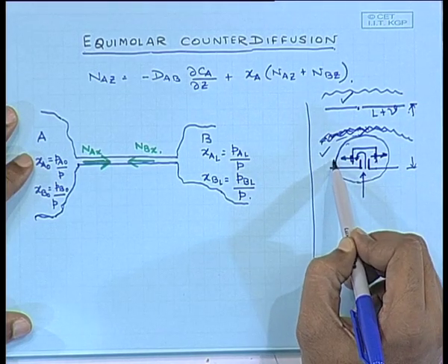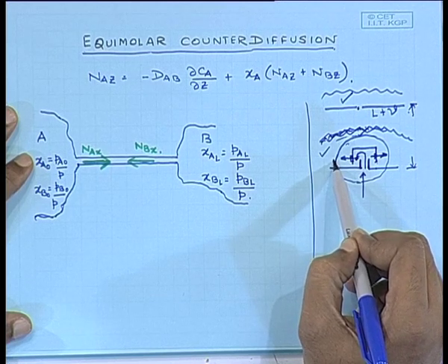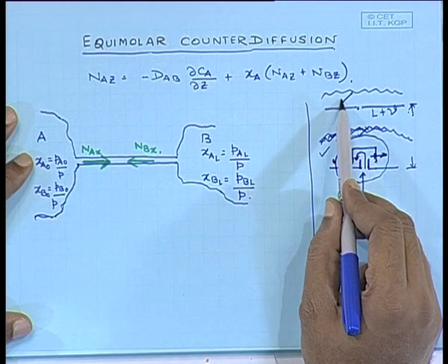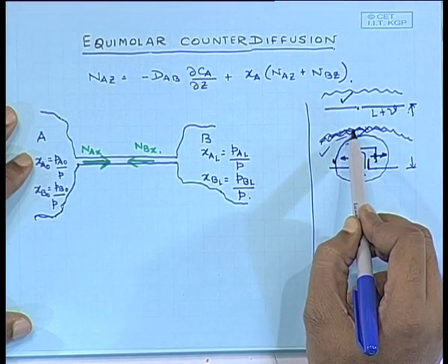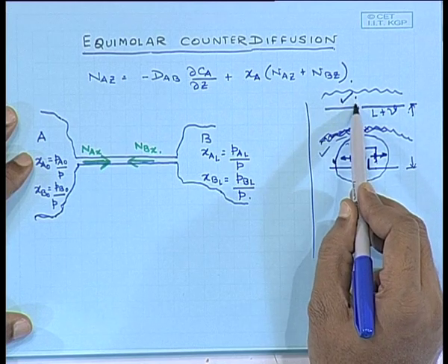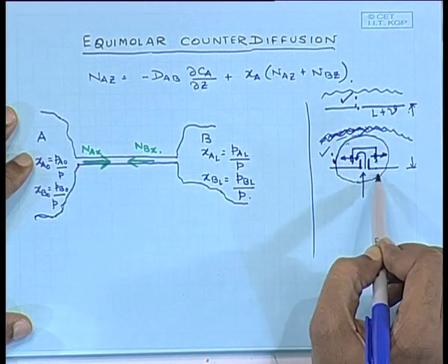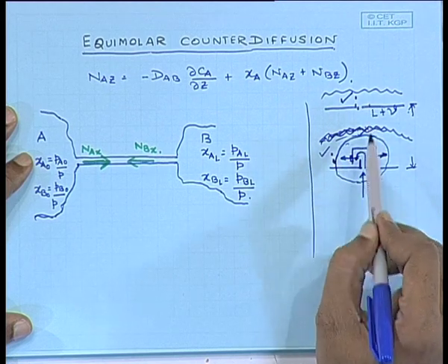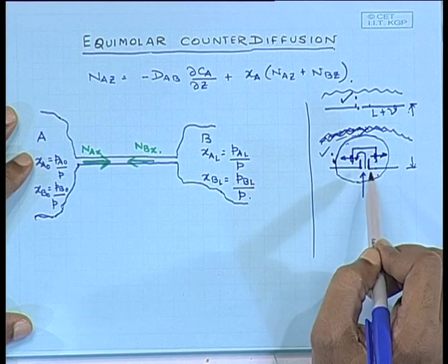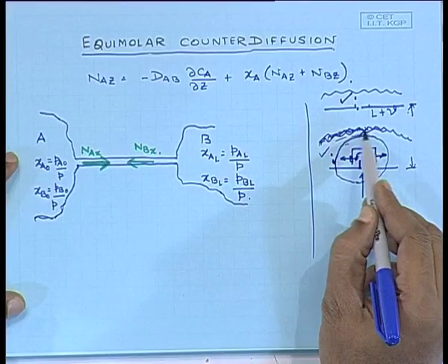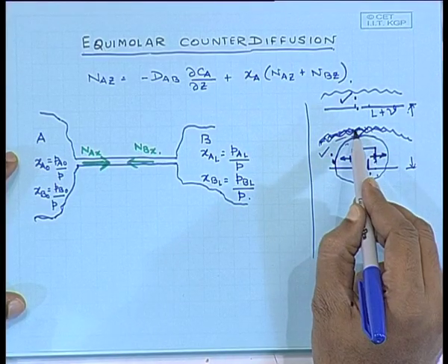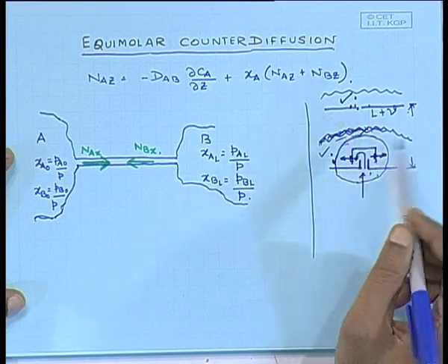This one being situated at a lower point should be more concentrated in the less volatile component compared to this one. So, if you let the foam, which is a mixture of liquid and vapor, reach the previous or the upper plate, then you are making these two concentrations more or less the same, in other words short circuiting these two stages. So, if it is a foamy liquid, you would provide more separation between two such stages, but you do not really want a non-foaming system. If it is 100% non-foaming, then you are going to have less contact between the liquid and the vapor. So, you want a moderately foaming system such that you have better contact, but not very high foaming such that it reaches the previous or upper plate. So, these are the conditions.